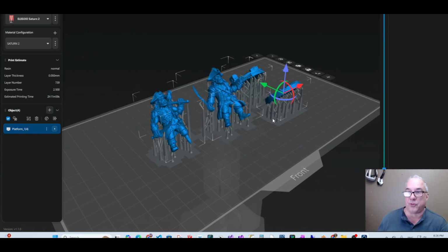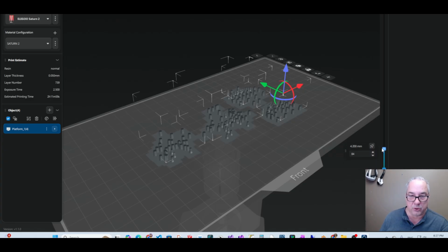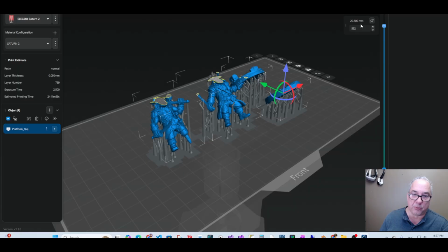We've exported the slice. By the way, this is what the slice looks like. If we drag this down, when we 3D print this, it starts at the bottom and it's upside down, and it prints by curing UV resin with a UV light. As it builds up upside down, as the plate lifts away from the vat bottom, it just builds it up from top to bottom like that, right?